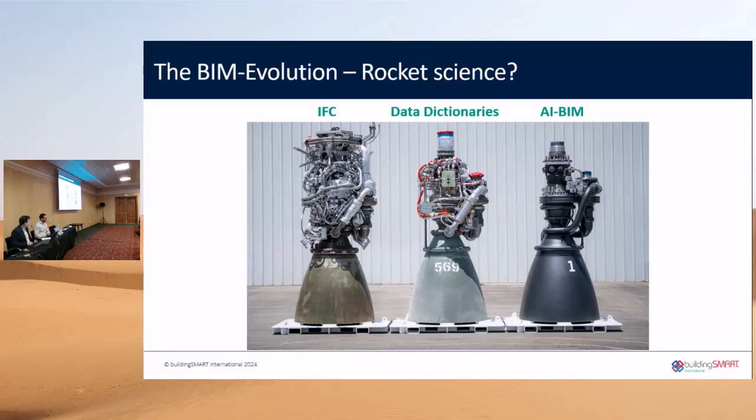What we also struggle with is that there are lots of tools that can generate the IDS and that can check the final IFC model against the IDS, but nobody really can say how you fill it in. So you need some automated tool that allows you to fill the actual values there, and that's something that's missing at the moment.